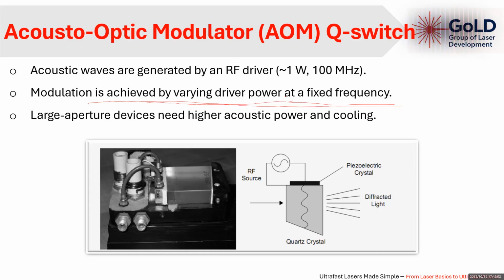Also, if we are using a very high power laser and this device is installed in the cavity generating very high power, we may need some cooling for this quartz crystal through which the light passes. But this is an extra thing. Usually we don't need water cooling, but if it's very high power, then we need water cooling. The main purpose here is for you to understand how this switch works.